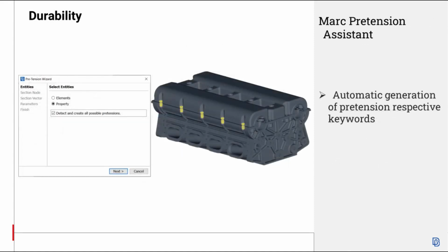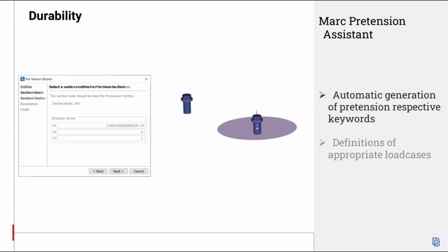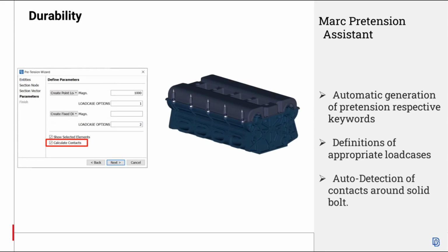A stepwise assistant for the automatic creation of all possible pretensions for the MARC solver, including the generation of the respective keywords, the definition of the appropriate load cases, and the functionality to generate the appropriate contacts around bolts, is now available.